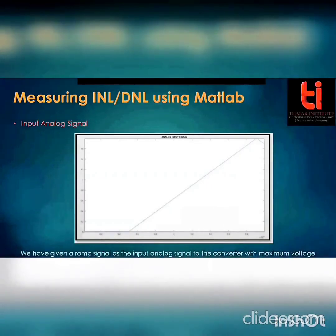For measuring INL and DNL using MATLAB, we give a ramp signal as the input with a maximum voltage swing of 1.8 volts, varying from 0 to 1.8 volts. The output of the converter is this, and the number of codes comes out to be 57, which means some codes are absent, because ideally for a 6-bit ADC the number of code bins should be 64, but we get 57 codes. So 7 codes are absent.